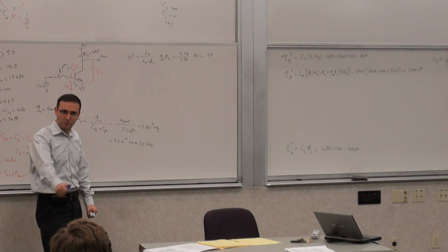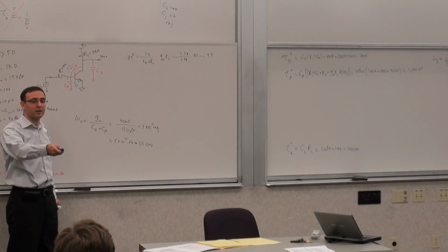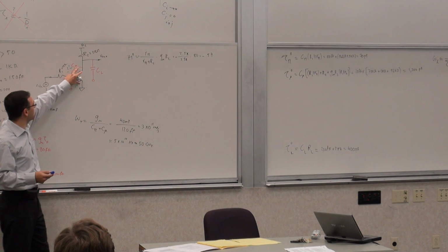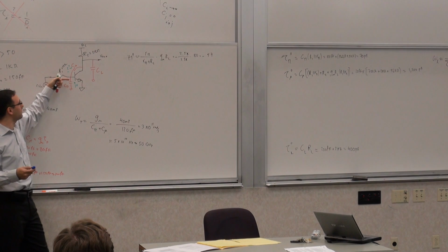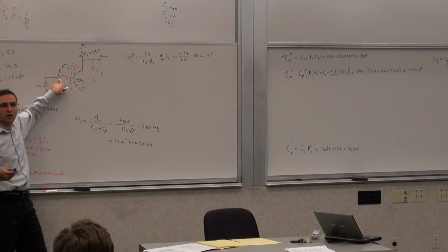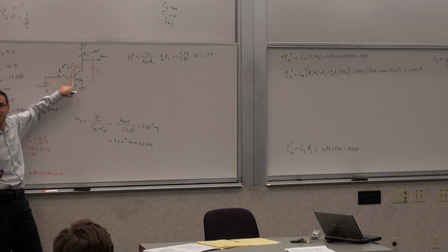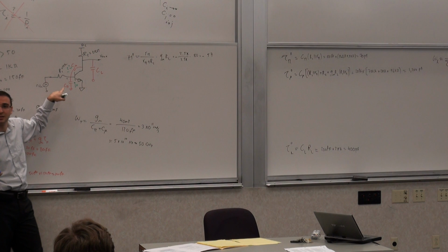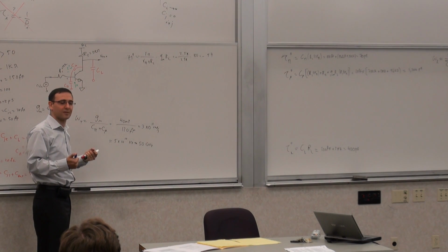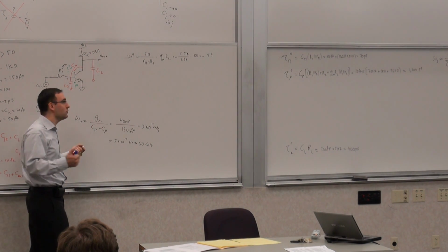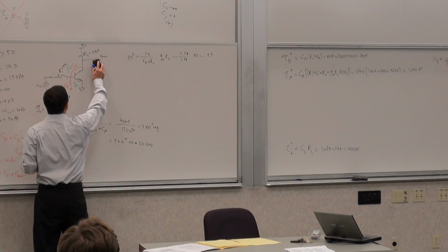is that its input impedance is very low. It's 1/gm. If I replace this with the common base by itself, what happens is that the common base input impedance is going to be 25 ohms. And this is going to be 1 kilo ohm, so that's going to kill all of my gain right there. Because the voltage divider will be 25 ohms divided by 1 kilo ohm, so that's like 1 over 40 almost. So it attenuates my signal by a factor of 40 right there at the input. So that doesn't work. So we know we have a trick for that, right? We have a cascode. So we use the common emitter input, but then we add a common base.